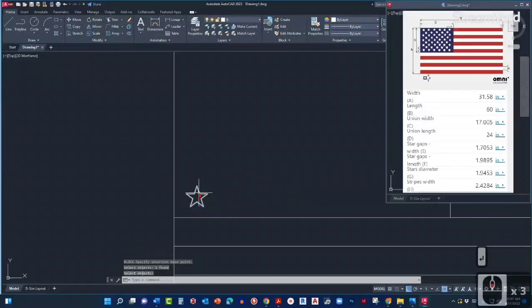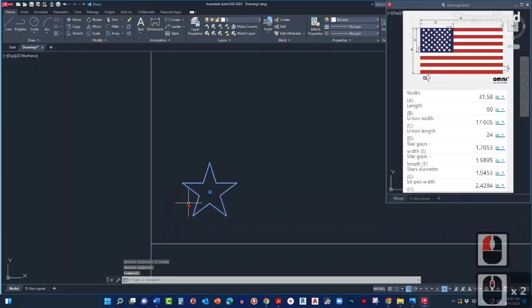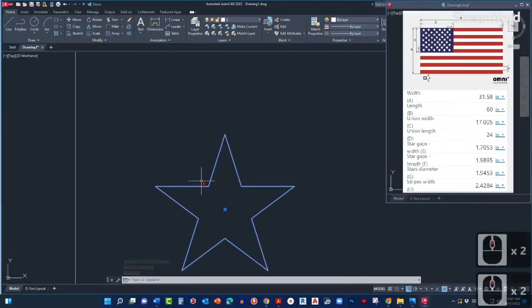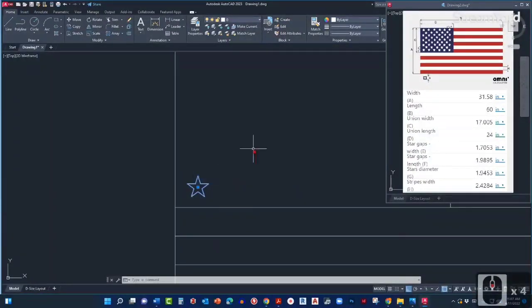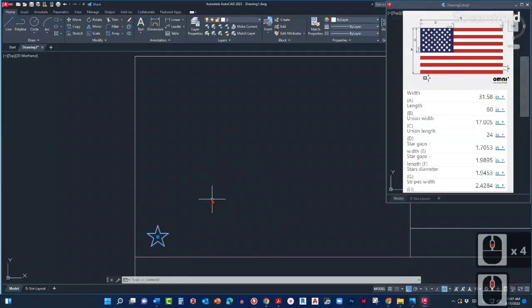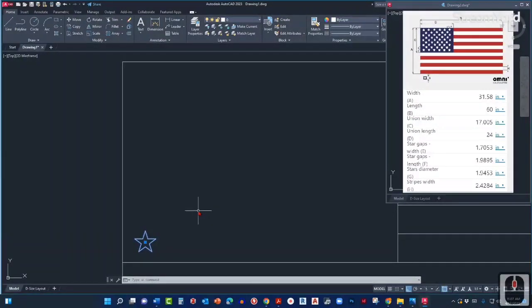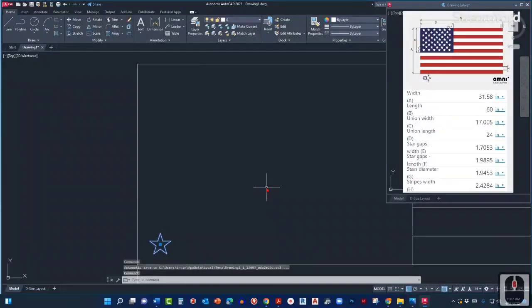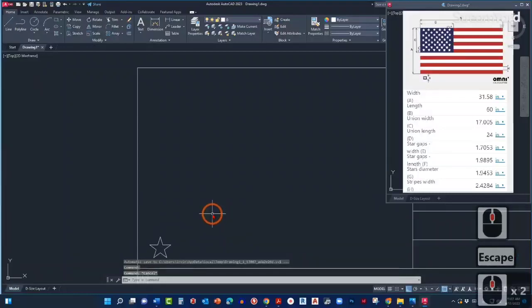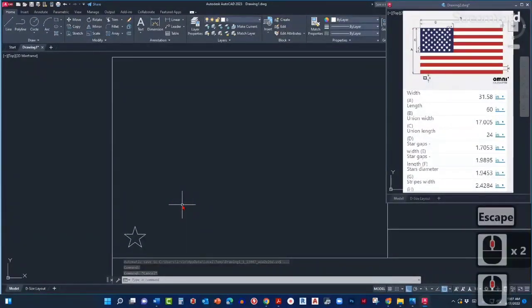So now what happened is that if I select this start, this is not a polyline anymore, but it is a block. So a block that if I hover, you can see it says block reference. So again, block is an efficient way to update objects, and in the future, you will see how all of the other stairs will update automatically. So let's keep moving, and now let me introduce you another command that is called array.